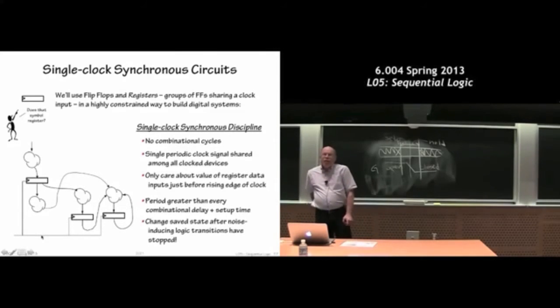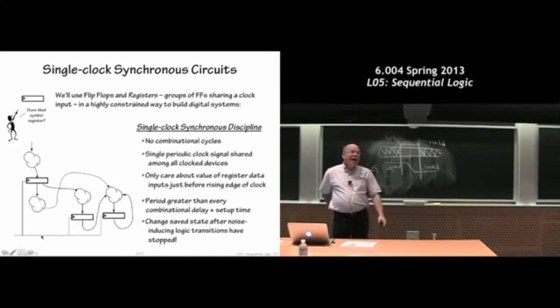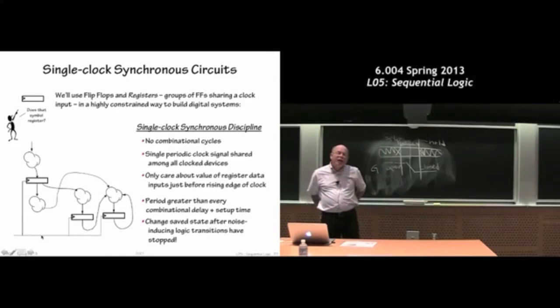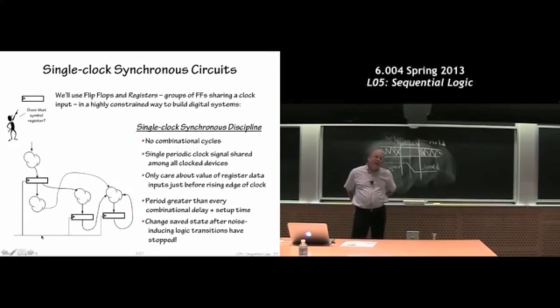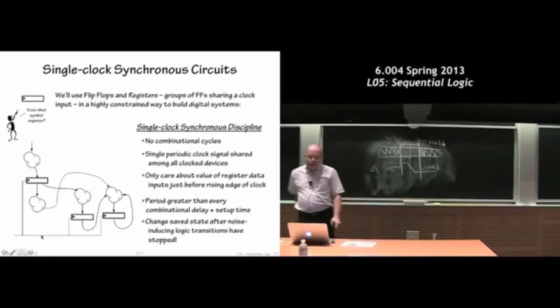So what we're trying to do is adjust our memories at the quietest moment of time. Circuits that have multiple clocks start having issues with the fact that you're changing over here, which might produce some noise just when I'm hoping to update my memory, and that noise might corrupt the value I'm saving. So multiple clocks are actually engineering challenges that you probably have to be careful about.